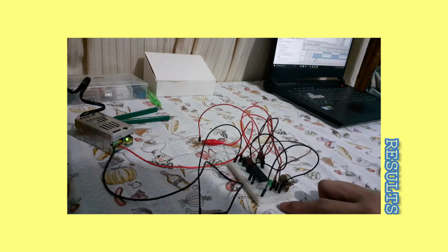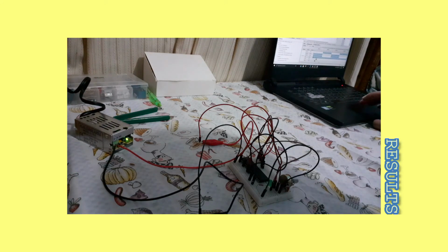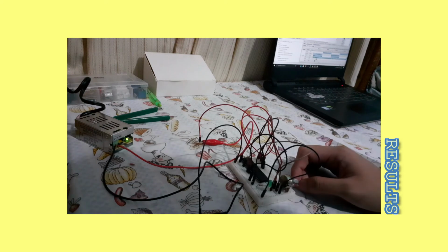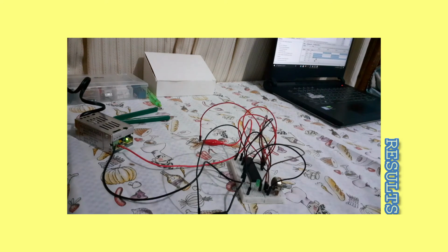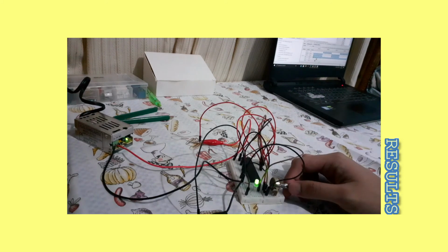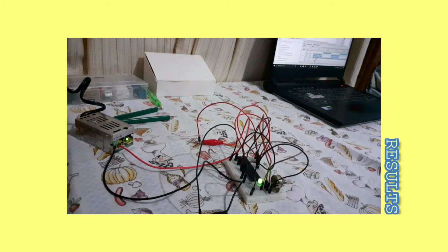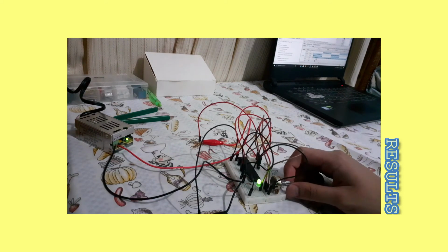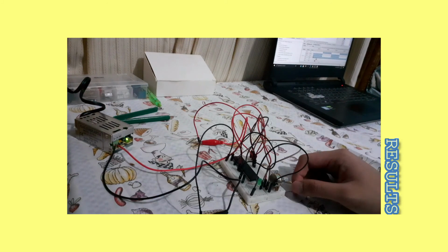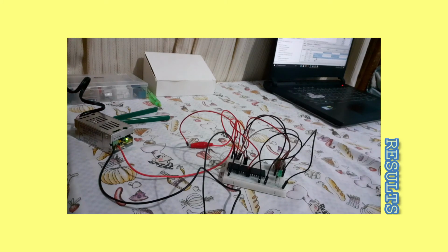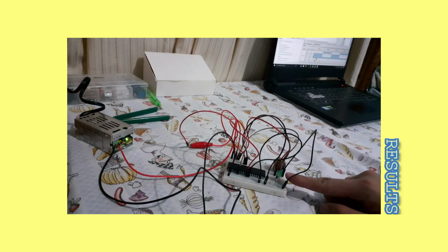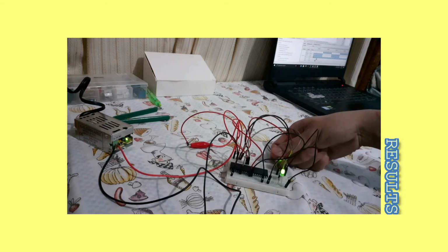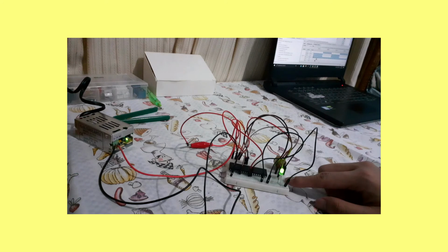So the LED does not light up. Therefore, with reference to our code, the value given by our input is greater than 512. Therefore, the output is off. So if we turn our potentiometer to the right, it lights up. Therefore, the input is less than 512. So again, if we turn our potentiometer to the left, the output is 0, which means the LED is off. Then if you turn it again to the right at maximum point, the result is 1, which leads to the LED being turned on.